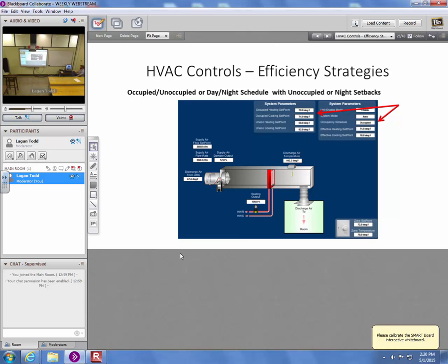Go ahead, Brian, you were going to. No, I was going to say, this enables small, constant adjustments rather than big periodic adjustments. Let me make sure I understand your question. By nature, this system is constantly making little tiny adjustments. Yeah. Instead of short cycling, like you have said in the past. Yeah, it's related, it's a little different. Compared to some other systems that would have more binary, open, close, on, off kind of control.